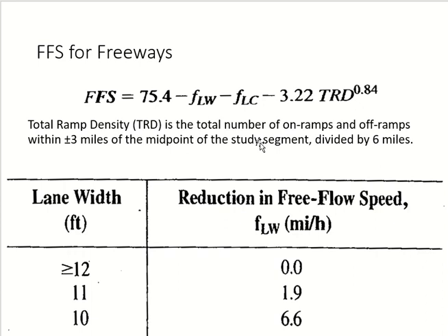There is a standard value. Go to the table, you will see the standard value where the factor is 0. But what is my point? You are doing the design. They did not give you any values. I have to assume values. I will assume standard. If I assume standard, the factors become 0. Clear? So the only thing left is TRD. TRD is given. So what is my free flow speed?